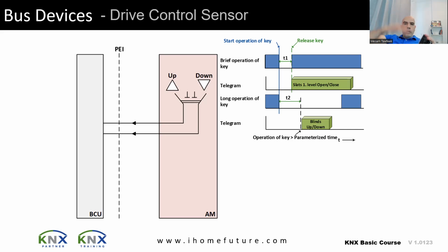going up or down, opening or closing, because they have a travel period for the motor to go. Okay? And if I do a short press, it has two actions. In case the motor is working, I mean the blinds or the curtains are going up or going down and in movement, when I press here, the movement stops. And if it's not in movement, if it is already standing still, when I do a short press here, it will move up or down with a specific step. So not going up or down all the way, but a specific small step.